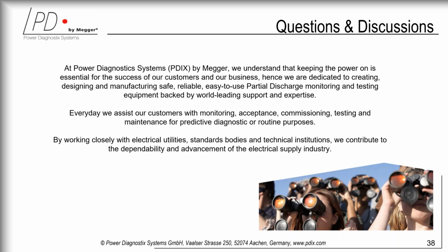Generally speaking, transformer factories or power utilities that buy new transformers will install them right from the get-go. People that have had transformers in action for a lot of time, and I think in the US and Canada this is the case, there are transformers there for 30, 40 years. I think they are a prime example where a monitoring device should go, because at any time we can catch early partial discharge and avoid any catastrophic failure. So thank you so much for the opportunity to answer these questions, really interesting.